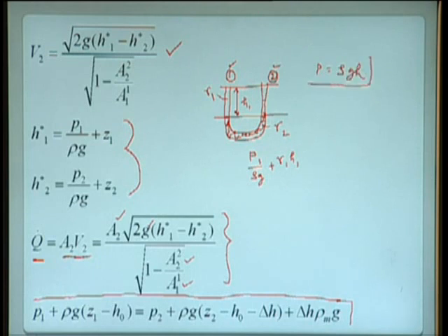We know the relation between pressure and height of the fluid. So, this height or column of the fluid will exert pressure, and the magnitude of that pressure will be equal to gamma 1 H1. This must be equal to the pressure at this point. So, what is the pressure at this point?